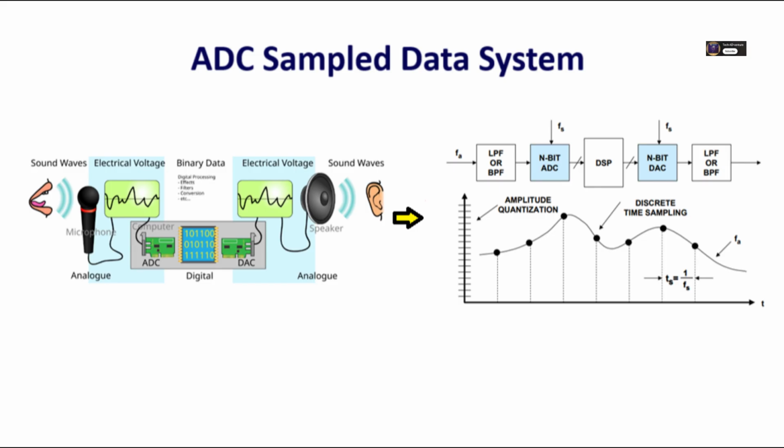If you sample too slowly, you'll completely miss rapid changes in the signal. It's like watching a strobe light. And when you try to reconstruct it later, it just won't look anything like the original. Right. The Nyquist rule is fundamental here. It basically says that to accurately capture a signal of a certain frequency, F, you need to sample at least twice that frequency, 2F. Ah, the Nyquist frequency. Exactly. If your sampling rate is too low, you get this weird effect called aliasing. Higher frequencies actually appear as lower frequencies in your digitized signal.